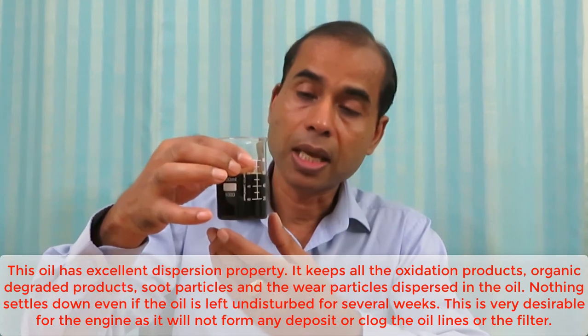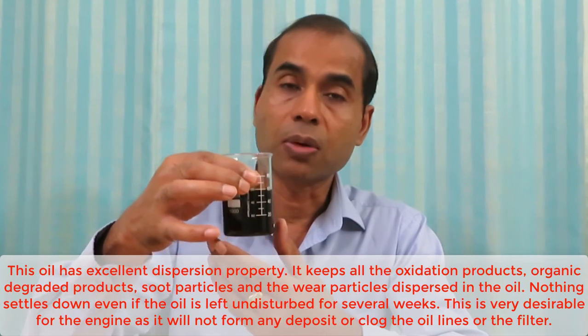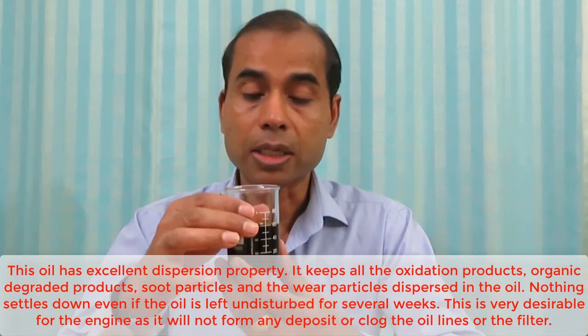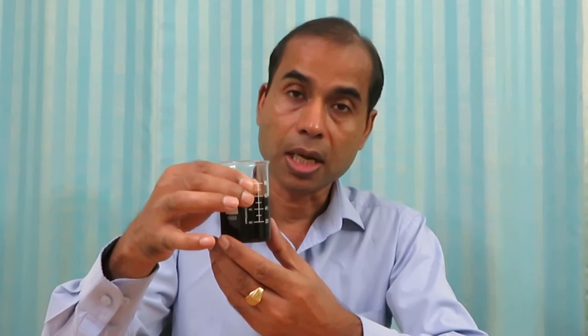Although this has a lot of degraded and oxidized materials, still it can work because all the products of oxidation and wear particles are still suspended inside the liquid, inside the lubricating oil. And lastly, I would like to say that lubricating oils contain a lot of sulfur and phosphorus compounds, and therefore these oils are quite toxic for the environment, and the disposal is a big problem.